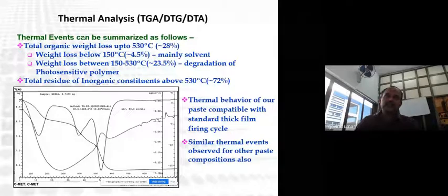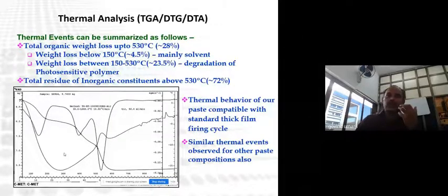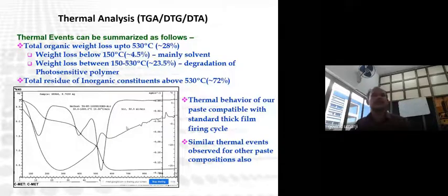This is required as a parameter for our manufacturers. They require to know this parameter. So this thermal behavior of our photopattern-based composition is typically compatible with the standard thick film firing profile, and similar thermal events were also observed for other paste compositions.